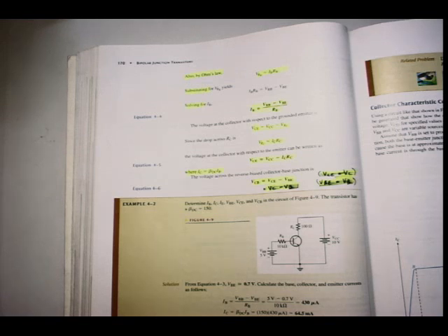VCE, and in this specific circuit's case, VCE and VC will be the same thing because there's no resistor at the emitter, so there's no voltage drop. It's going to be the supply, VCC, minus VRC, the voltage drop over RC, Ohm's law, IC times RC, but I can also use Kirchhoff's law. We actually did use Kirchhoff's law. And then the voltage at the collector with respect to the emitter, VCE, which is actually the same as VC, is VCC minus ICRC, which is the volt drop over RC.